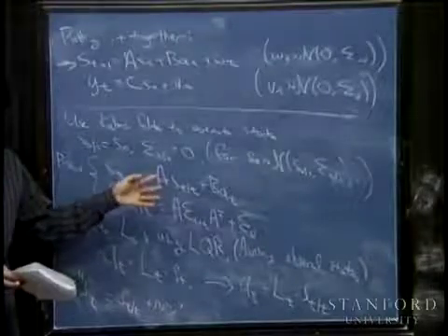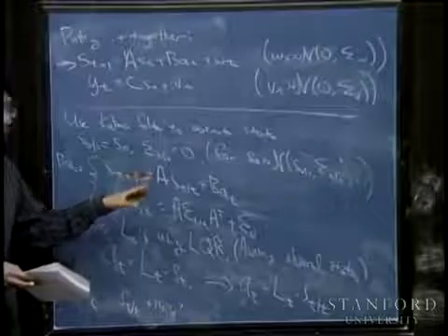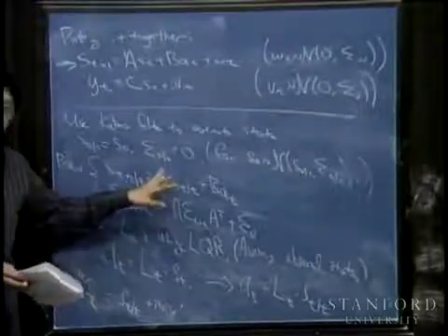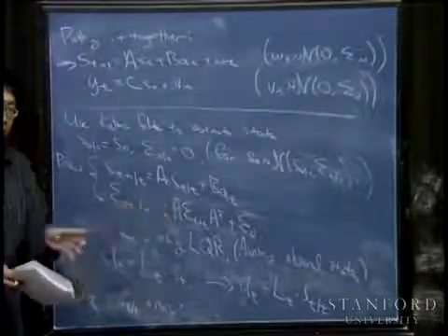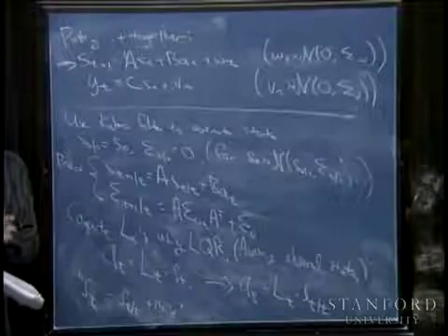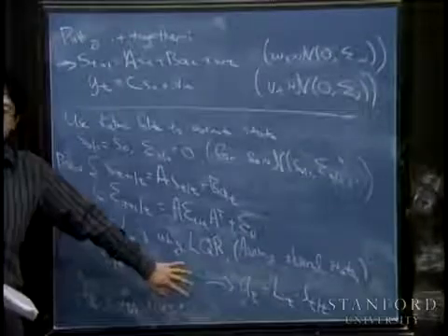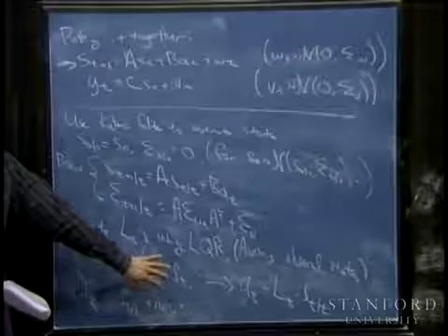It doesn't hold true for many systems. Once you change almost anything, once it's nonlinear or has some other noise, this will no longer hold true. You can estimate the states and plug that into a controller designed assuming you could observe the states fully, but once you change almost anything, this will no longer be optimal. But for the LQG problem specifically, it's convenient that you can do this.